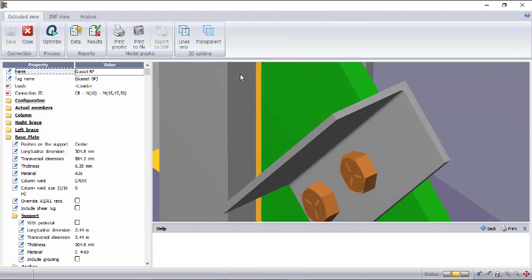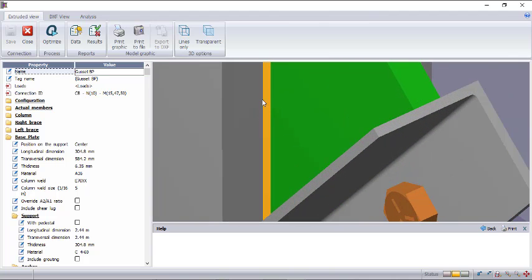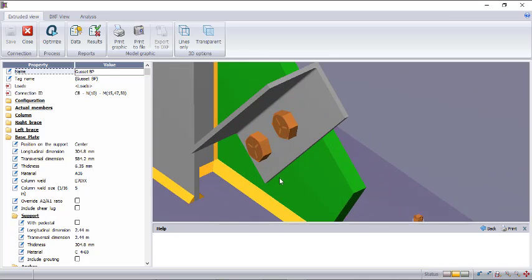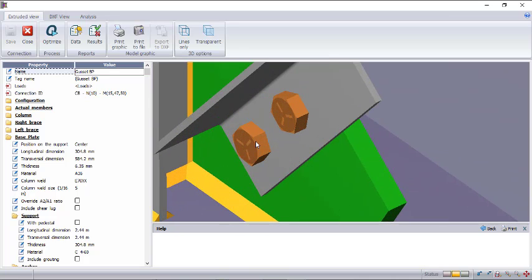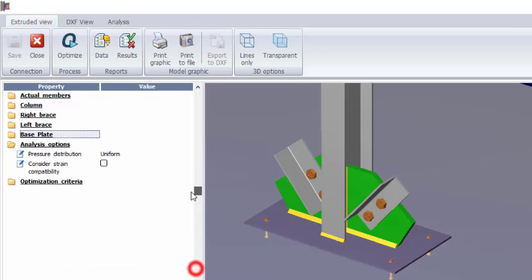It is also connected to the column. You can see this particular connection you are seeing here. That is also a weld connection. That's a direct weld. And then you can see that it is also connected to the angle bar with a bolt. Okay, so that is 3 connections for the gusset alone. All right, so that is why the name is called gusset base plate. Okay, so the connection is basically with the gusset.